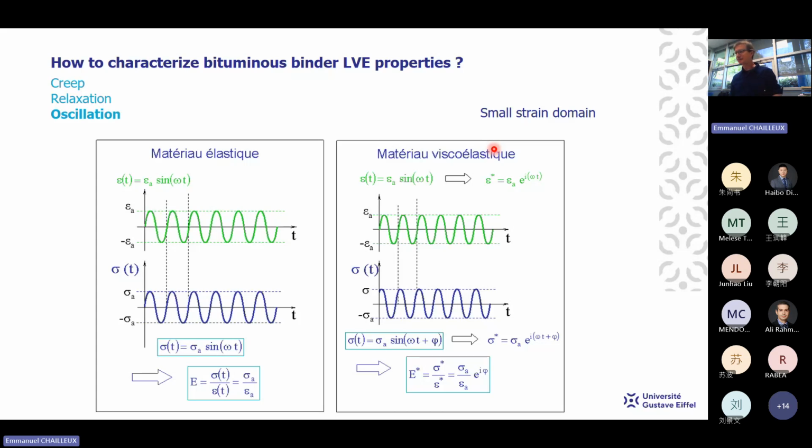With this type of procedure, we apply a sinusoidal strain or stress, and we measure the consequence, so the sinusoidal stress or the sinusoidal strain. What we have to know is that if we are in the small strain domain, so if you don't damage the material, the response to a sinusoidal loading mode will also be sinusoidal.